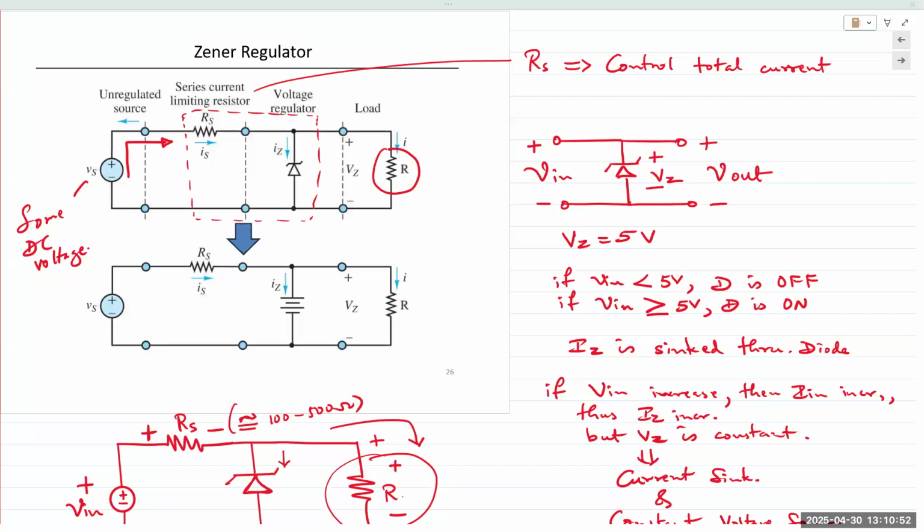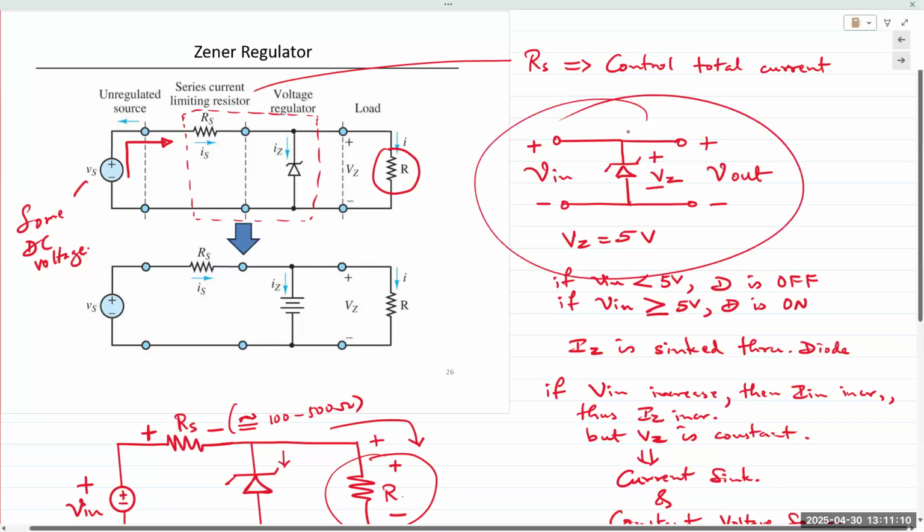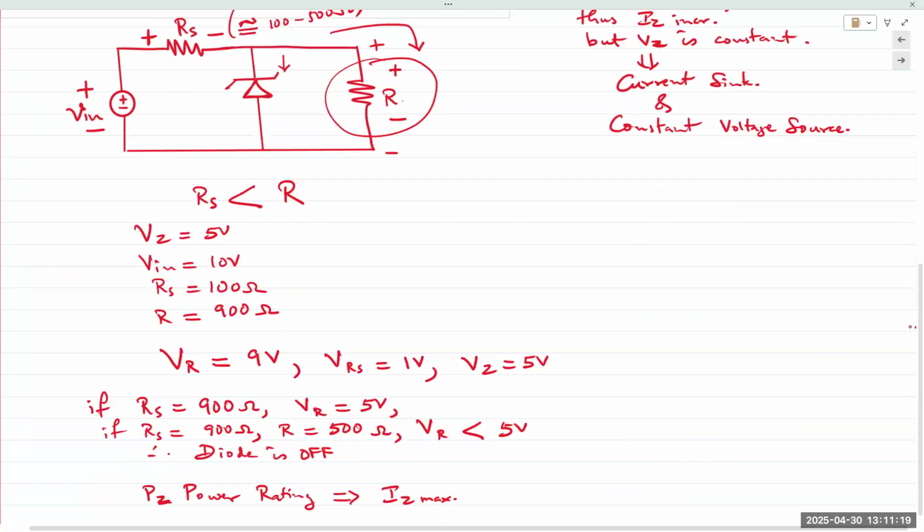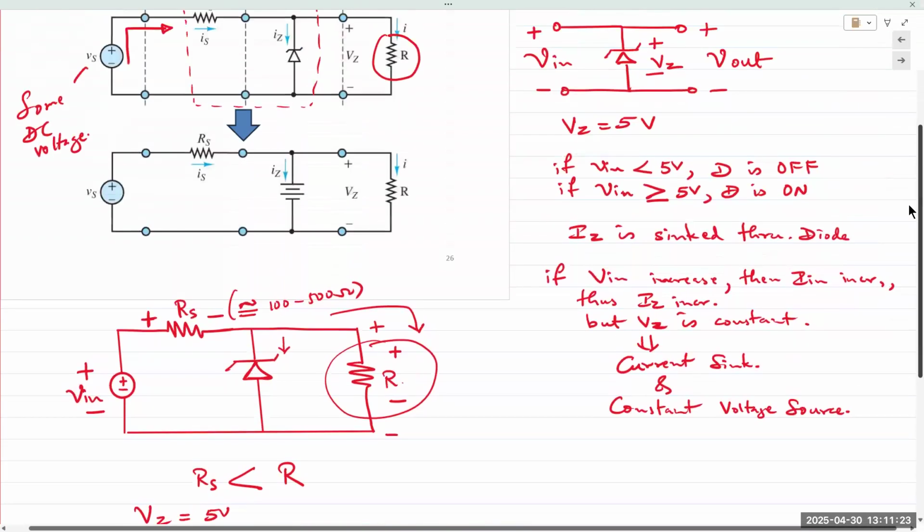All right. So we first began looking at a voltage regulator circuit using a Zener diode. Voltage regulation uses the property of a Zener diode that it holds the voltage across its terminals constant, right? And so we first look at an ideal circuit where you're simply applying V_in from the left, obtaining V_out. Obviously, in real life, that's not possible, right? Because a voltage source will supply its rated voltage. So we could never have V_in equal to VZ without having a resistor in the middle.